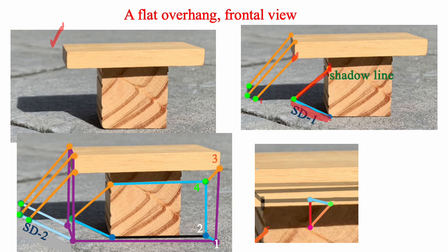When we set up our seats then, we need to make sure that the shadow direction parallels this first one, and then we can find these different intersections on the ground. Now, to find the shadow under the overhang, you can start with the seat over here that's under this part of the overhang and draw a light ray through its bottom. And we get an intersection here as if this whole surface is extended. You could see that the shadow direction is here, and then it goes up this imaginary wall to go to this intersection. And that's the shadow line.